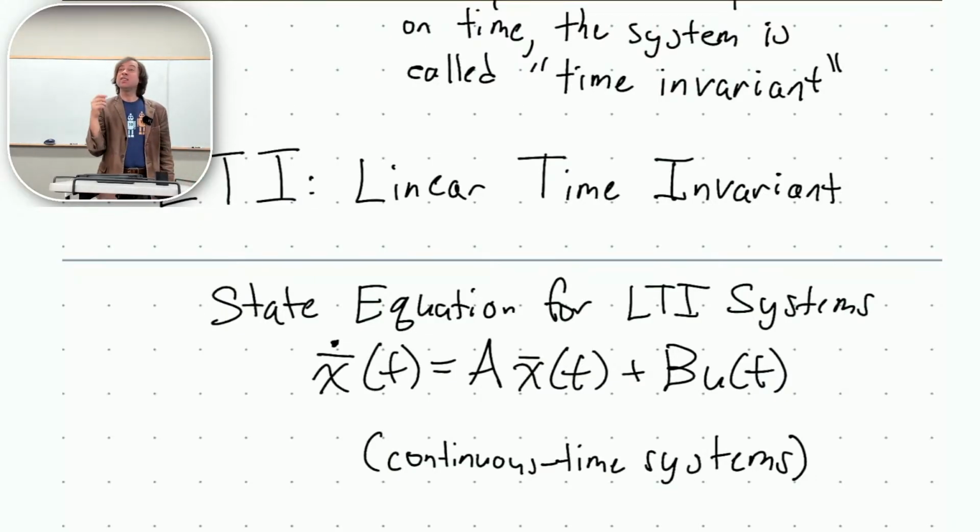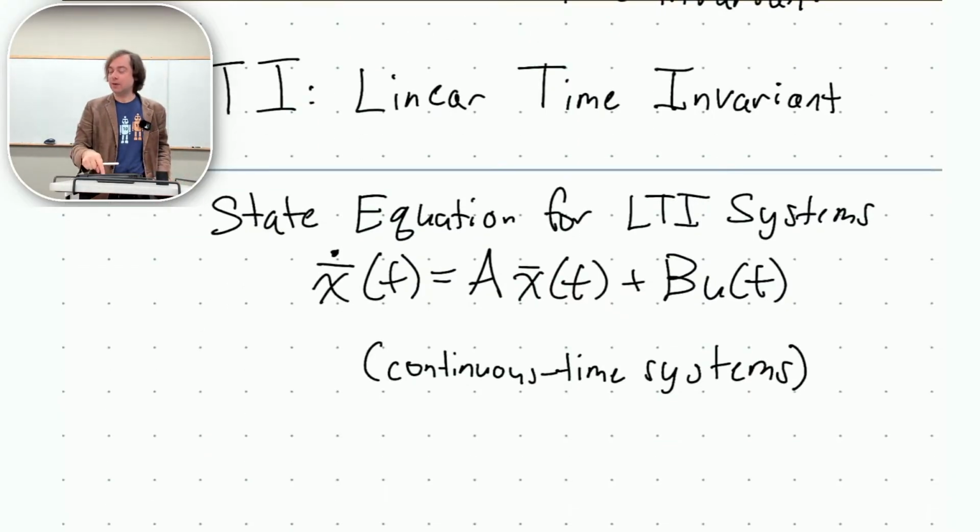There are discrete time systems where your system is on a clock. That there is no time in between those two clock cycles, okay? For which the equation is slightly different, for which the eigenvalue stability analysis is slightly different. But you can use a lot of the same tools. It's just like the math changes just a little bit, okay?